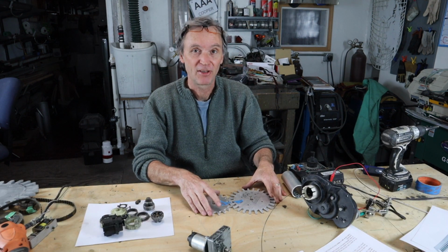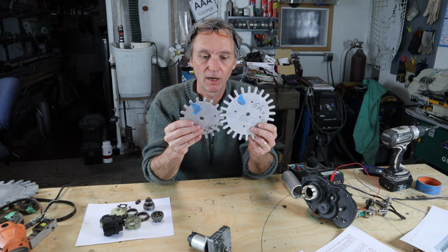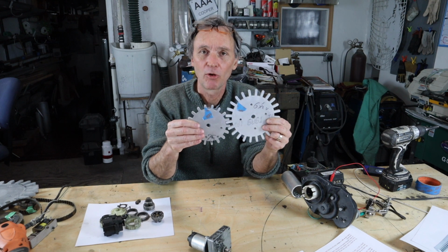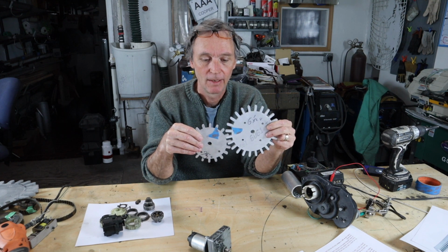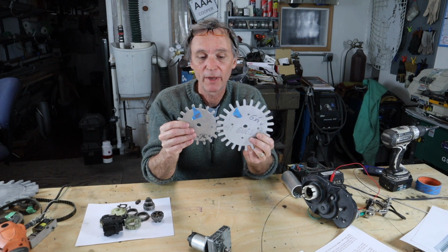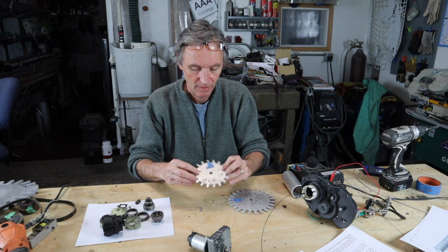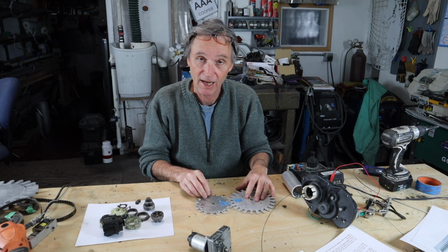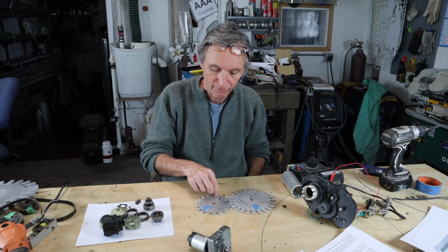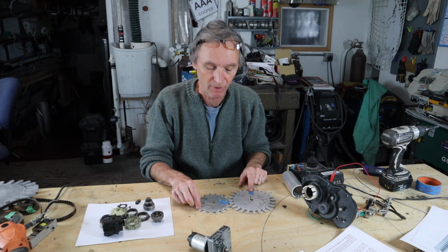Let's look in a little bit more detail. First, we're going to start with gears and pulleys. First, gears. I'd just like to point out these are not gears. These are actually part of a globe building project, but they all illustrate my point fairly well. Basically having teeth that intermesh and transmit motion from normally a larger to a smaller or a smaller to a larger. If we look at this, you see I've marked these very expertly. If we turn the small one a full revolution, the large one's only done three quarters of a revolution.